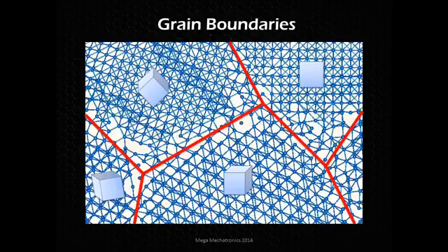So if you have smaller grains, more smaller ones, that's going to give us a stronger, harder material, because we're reducing the ability for that crystal lattice to deform and move around, because there are these deformities there, sort of like a wall stopping them from moving any further.